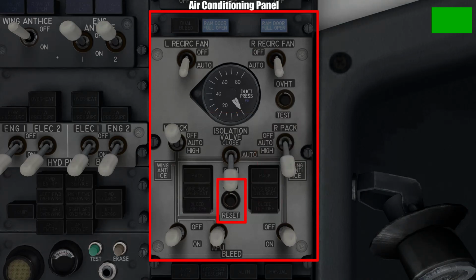This trip reset light is there to reset the malfunctioning pack system once it's done cooling down, to resume normal operations. Finally, underneath here, we have 3 air source selector switches to acquire bleed air from. On either side are the engine bleed switches, which when turned on take bleed air from the engines to then use for air conditioning. In the center is an APU bleed air switch, which allows the packs to use bleed air from the APU when on the ground to cool the aircraft before engines start and to also aid in providing the air for the engine start procedure.